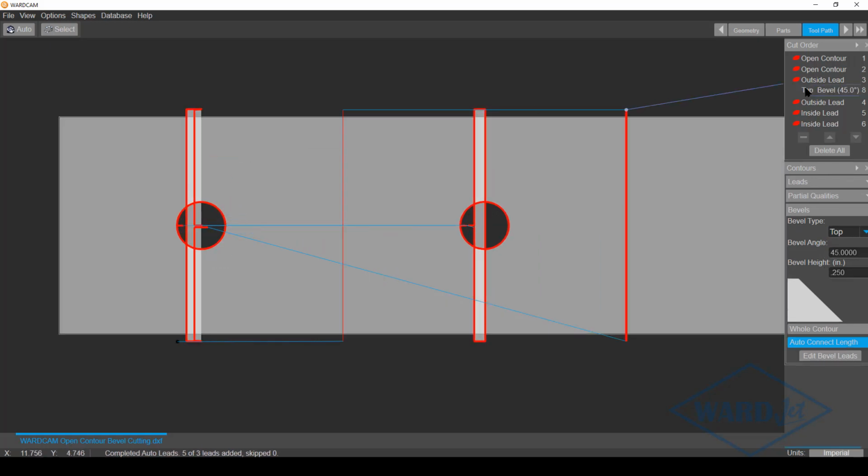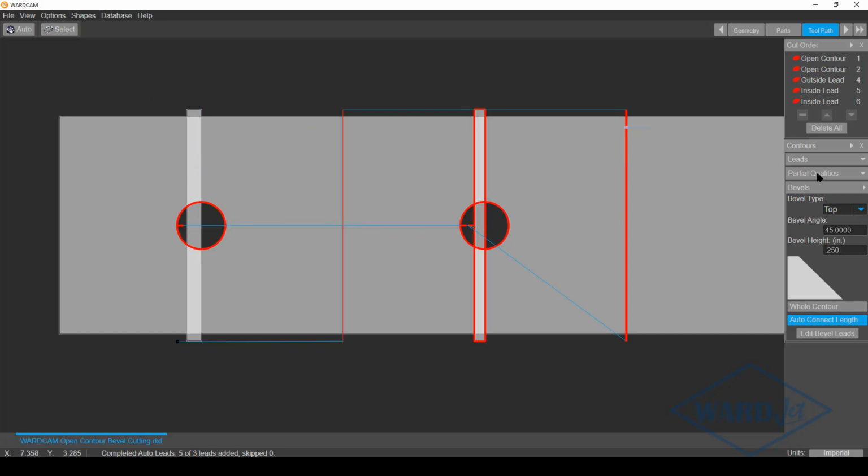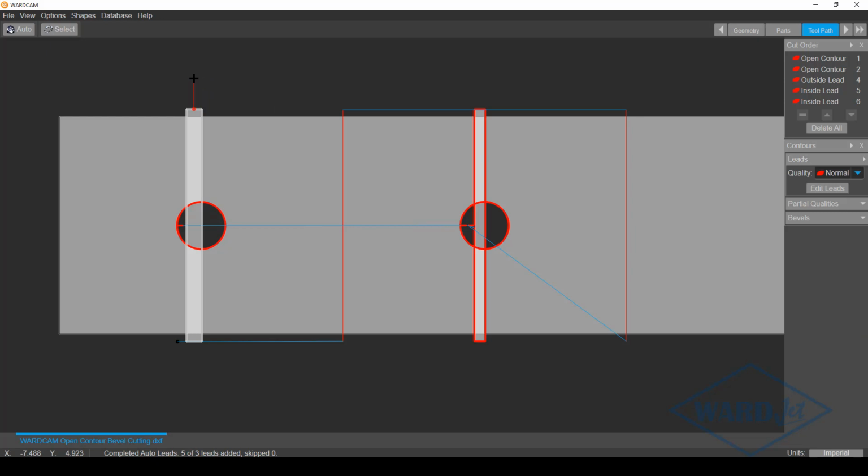Left click that in there, and when the material thickness and the bevel height are the same, your vertical cut and your bevel cut are tied together as one tool path, and you can't delete the vertical portion of it. So the workaround for that, as I mentioned, is just to make that bevel height 1/1000th of an inch more or less than the material thickness.